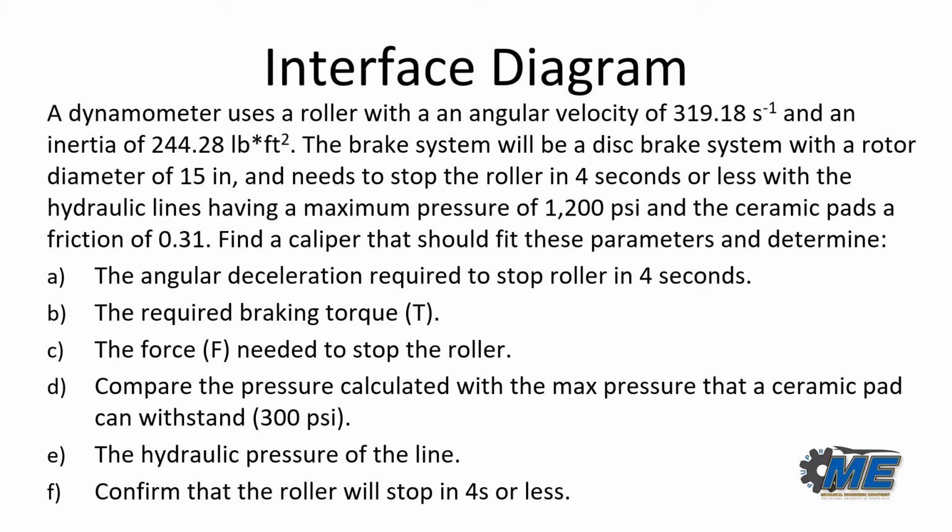Find the caliper that should fit these parameters and determine A. The angular deceleration required to stop the roller in 4 seconds or less. B. The required braking torque. C. The force needed to stop the roller. D. Compare the pressure calculated with the max pressure that a ceramic pad can withstand, which is 300 psi. E. The hydraulic pressure of the line. And F. Confirm that the roller will stop in 4 seconds or less.